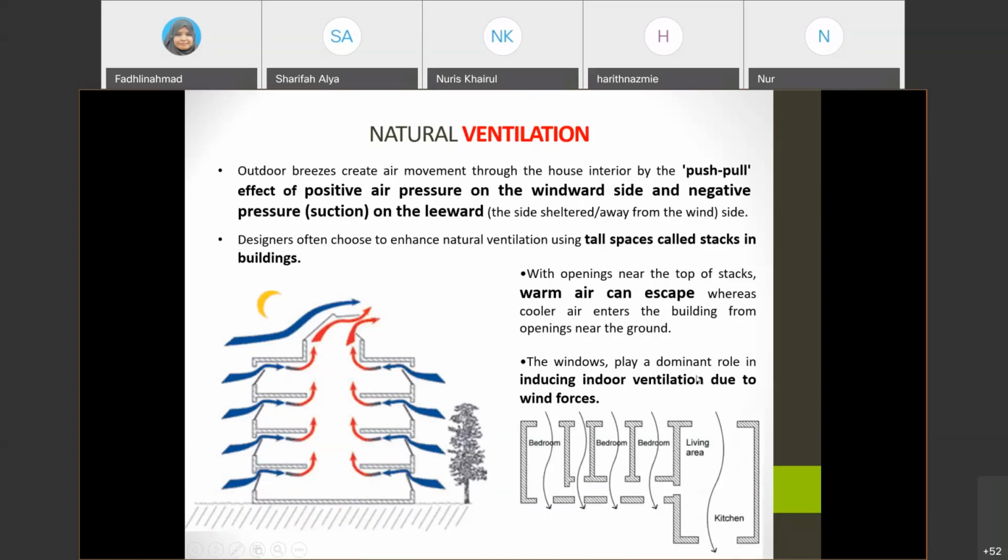this one is also an example of when you do your plan later, you need to know where is the best location to put all the spaces. For instance, for this one, they put in cross ventilation. So you will have one window over here and then another window over here, so that it will create cross ventilation between the spaces. Okay. What happens if you put all the solid things over here? What happened to this area, guys?